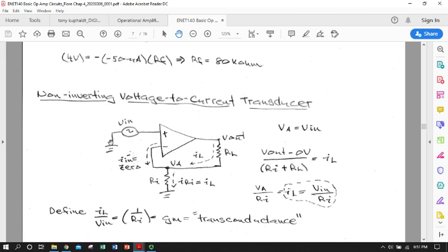And so there's a bit of a pattern there on input and output. So in any case, we have our voltage signal coming in. It's coming into the non-inverting terminal. And we have our V out, and it's connected in series to a load. And then to a node point, we've got an inverting terminal resistor, and it's R sub I because ultimately it's connected back up here and then down to ground.